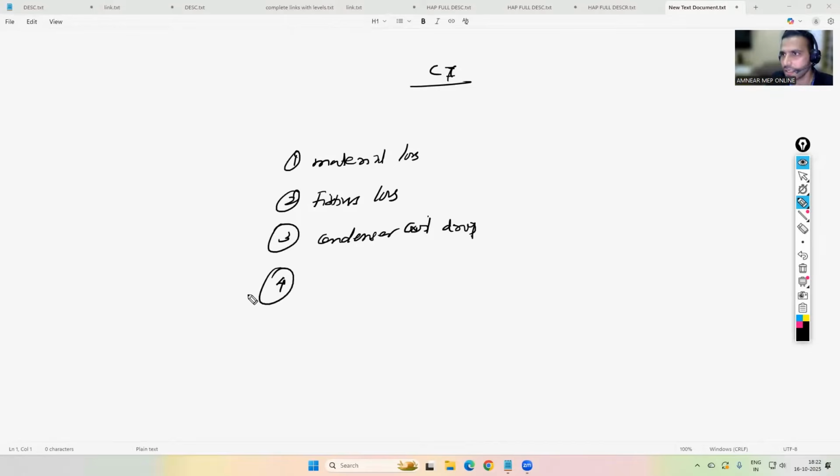The fourth one, definitely static head you have to consider. Sometimes the cooling tower might be located on the roof side, and the chiller might be located in the basement to avoid vibrations in a water cooled chiller. So static head also you have to consider there, how much gravity it has to overcome. The fifth one, residual pressure of the spray nozzle you have to consider.